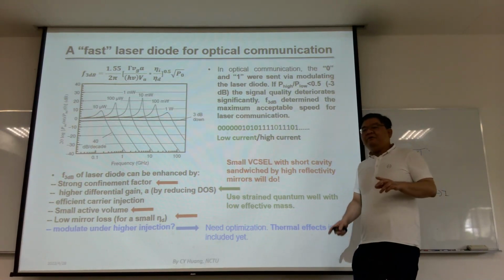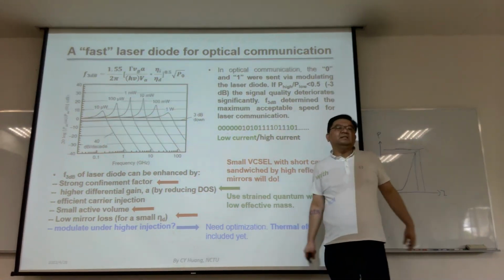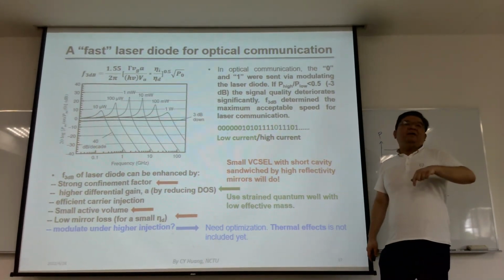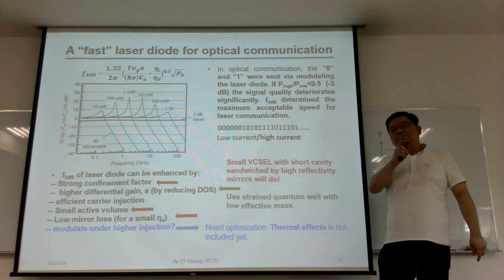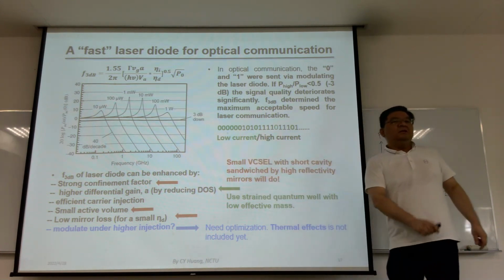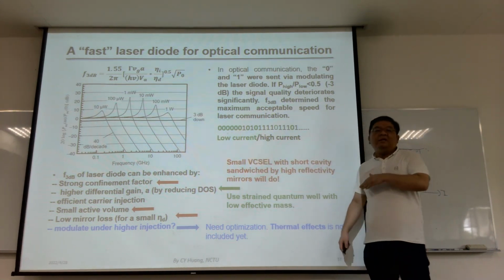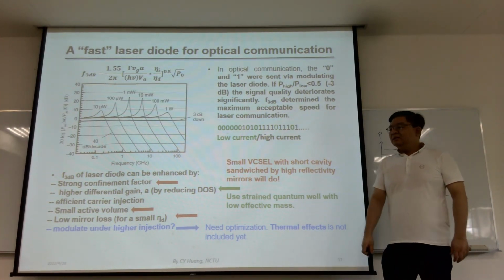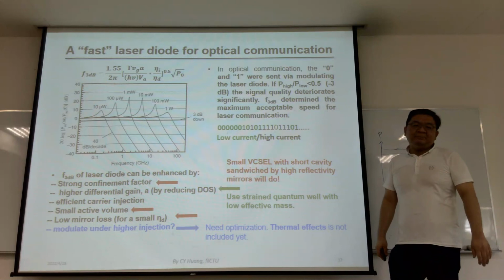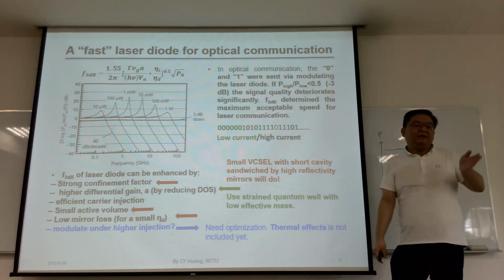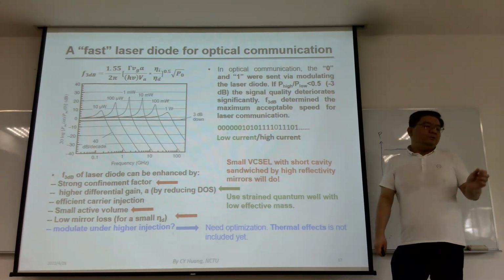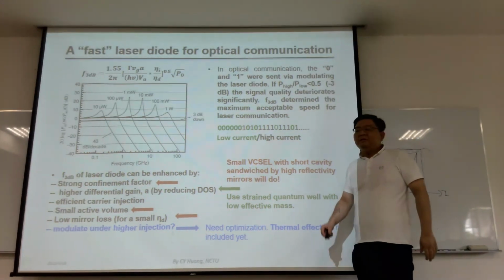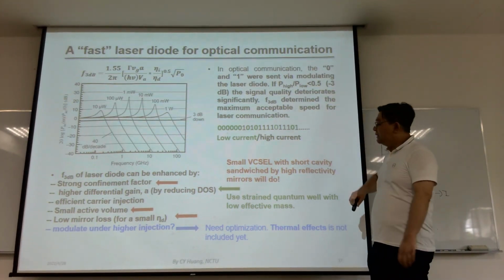However, for very, very long distance communication, like a signal from Taipei to New York, it goes back to the edge emitting laser, but that's not because it needs higher power. It's because the edge emitting laser can have more design to control its lasing wavelengths. That will also be a topic in the future.